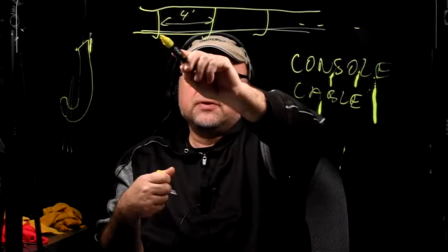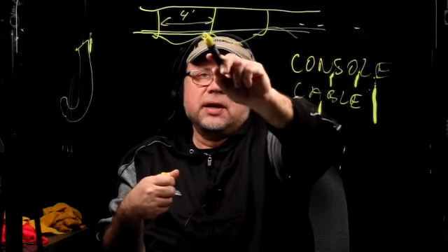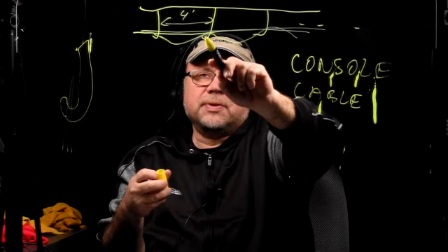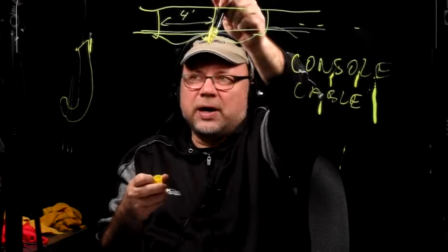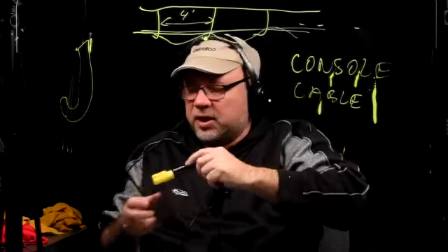Okay. Because if they're further apart, the cables are just going to start sagging under their own weight. Okay. And when there's a bundle of cables sagging, the cable on the bottom has it the worst, because the cables add up weight, and that's going to be the most stressful point for the wires. It's just like you're stepping on the wire here, right? So that's not good. You can actually compromise the specs of the wire.